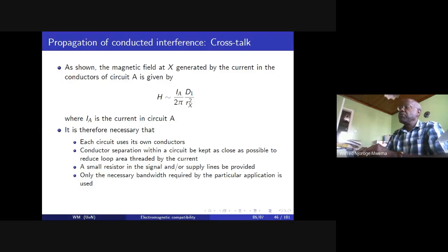Well, in terms of EMI or EMC, that one is very dangerous because the fast changing edges of the clock will represent frequencies from DC to infinity, that is to very, very high frequencies when you look at the harmonics. And therefore, it's necessary that we reduce the rise time and the fall time.